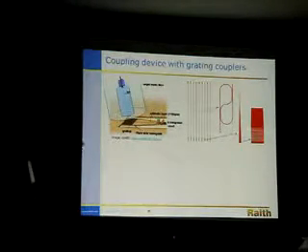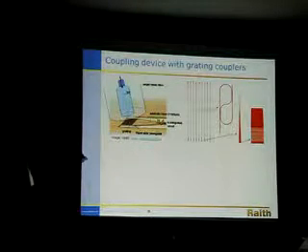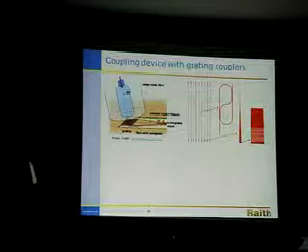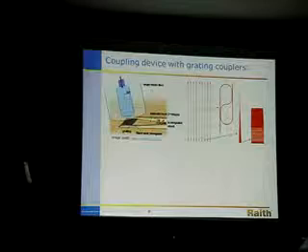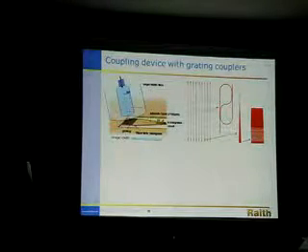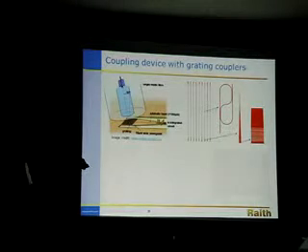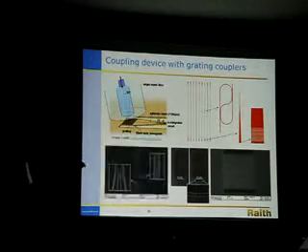Some examples of these are 2 millimeter long waveguides, just to give you an idea of what the photonics research community is asking for. This is coupling light from a fiber into the nano world using a grating coupler, tapered structure down into a nano photonic waveguide. And so just some of the results.